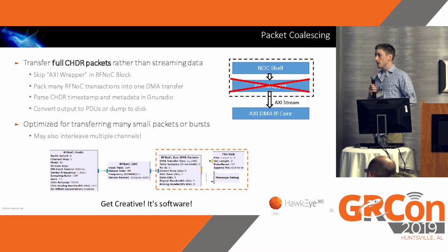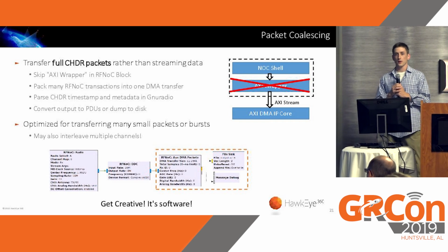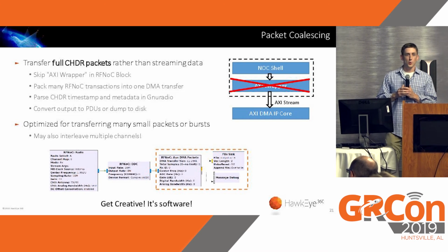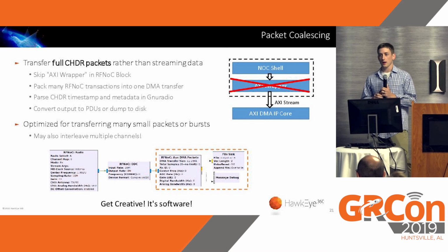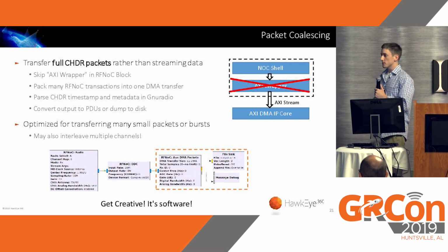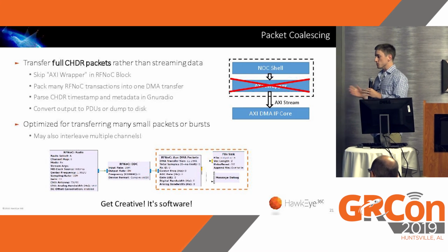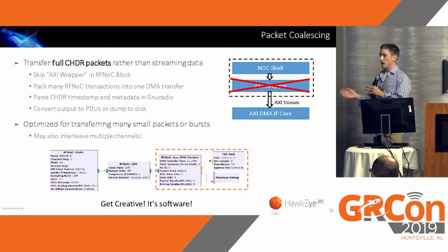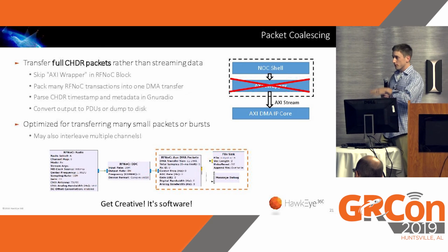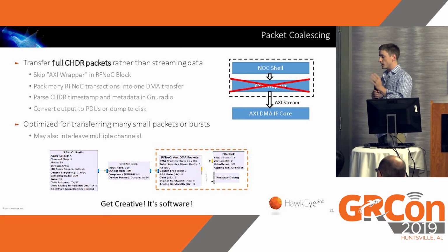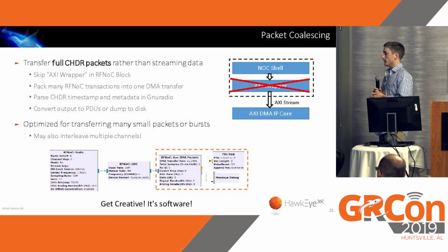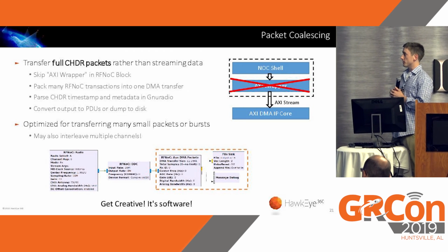And so our use case turned from one where we had continuous streaming data, and we wanted to write that into GNU Radio, to one where we had lots of small packets, probably 256 bytes or so, and each of those was self-contained. It has like a start time and some number of samples, and they're not really linked to each other. So based on the old streaming architecture, we cut it off if we saw kind of an inverse scenario, where we needed to interpret a timestamp differently.